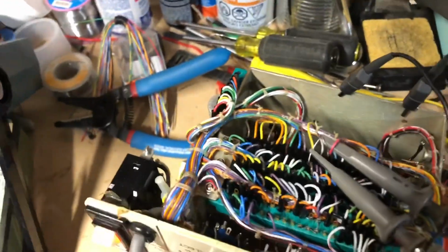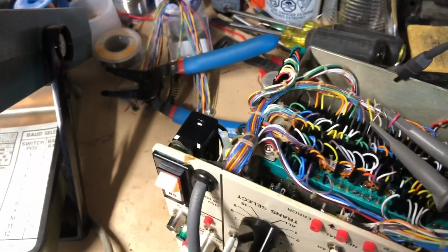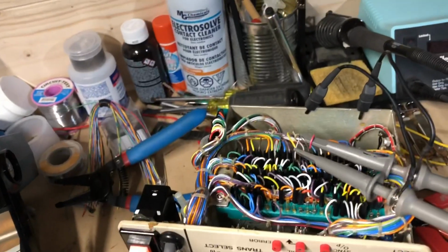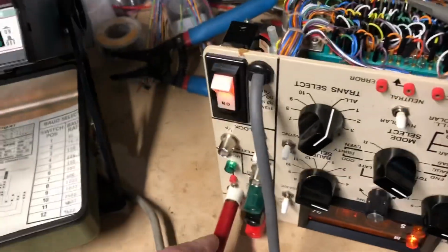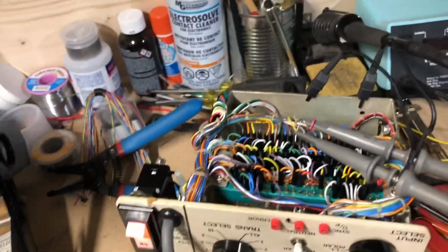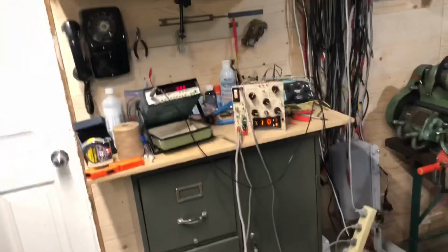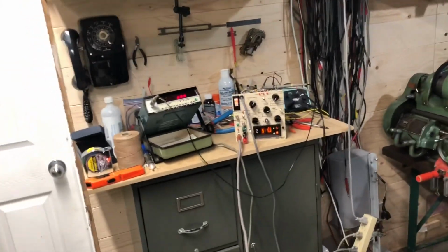All right, so I poked and prodded all over this thing, and I couldn't find any signal that was consistent. It looks like when there's a signal on the loop, it triggers the counter to count down, which makes sense. So they would trigger the counter for the width of a bit period to measure something. It's not a continuous clock.